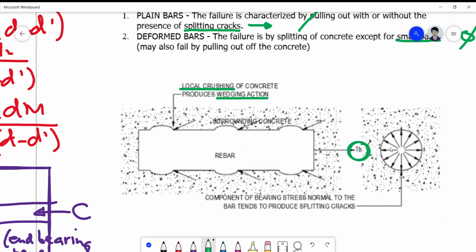If we take a look now on the inside of this reinforcing bar, by visualizing it inside a hole, we take note that when the concrete is pushing this reinforcement deformation here, there are protrusions at certain parts of the reinforcement that allow the wedging action to be mechanically possible, and allowing a stronger mechanical action between the deformation and the concrete.